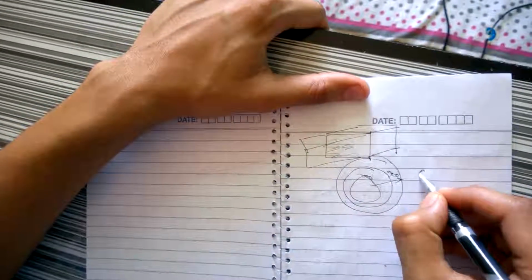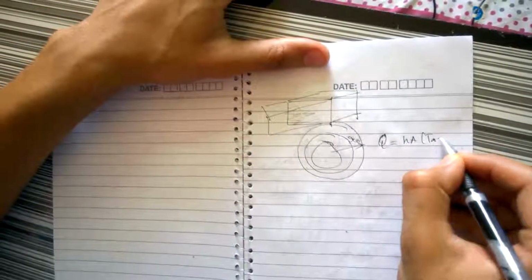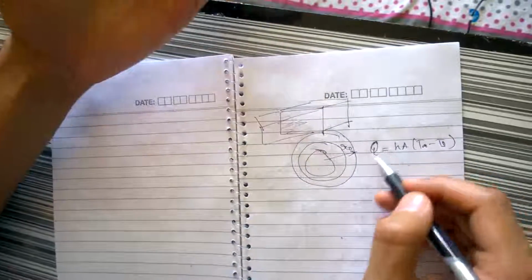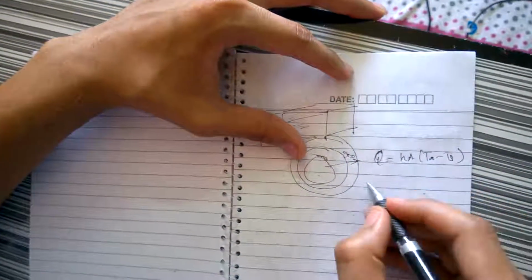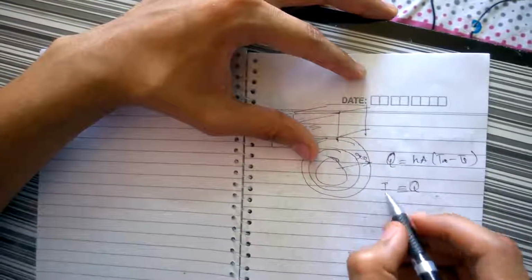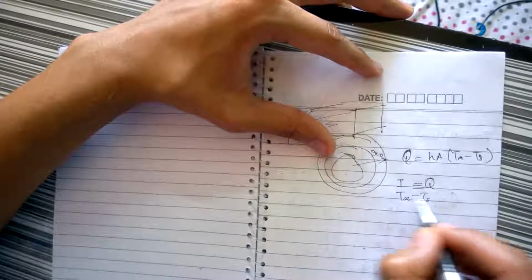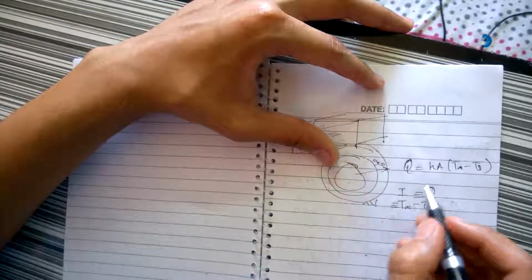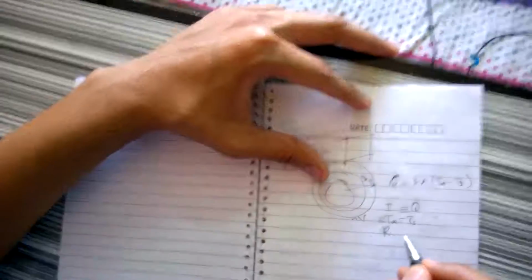We understand that for a fluid medium, we saw that Q equals h A (T infinity minus Ts) in the first chapter. Remember that a heat system can be equivalent to an electrical system, wherein the current is the same as the heat, and the difference in temperature is the same as the difference in voltage, the potential difference, right? And the remaining part, whatever we find in the expression, is nothing but the resistance.